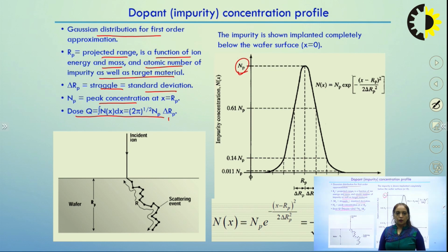So in ion implantation, when we implant with a very high accelerating beam, it will be implanted in this way. If you analyze this graph, this is the depth as we go down in the substrate, and here we have the doping concentration, right? Near the surface we have more doping concentration, and if you go deep down the substrate, the doping concentration will be less, right?